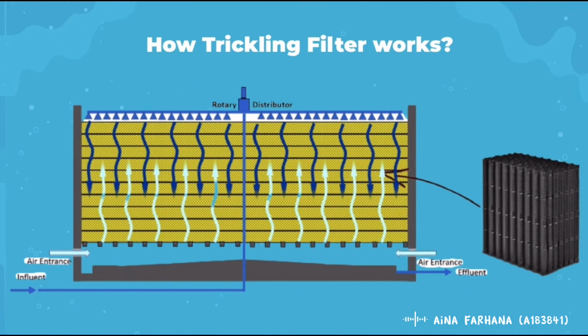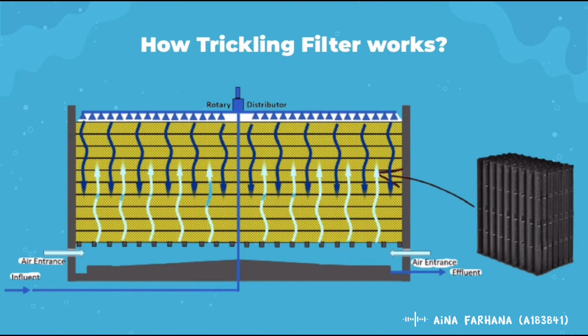How do trickling filters work? Compared to the activated sludge process, the microorganisms are not suspended in the mixed liquor but are attached to a fixed bed surface. Nowadays, the fixed bed surface is usually provided by structured plastic film media. The wastewater from the primary clarifier is continuously trickled over the first layer of plastic film media using a rotary distributor, while wastewater travels down to the bottom of a trickling filter across corrugated patterns within the plastic film media to ensure good water-air mixing.